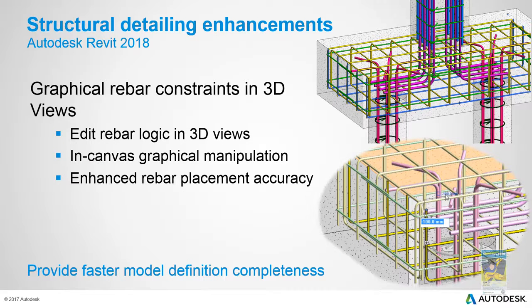And then in regards to rebar constraints, you can now modify them in 3D if you need to modify them. Sometimes it's a little easier to see and work with in a 3D view than try to manipulate that constraint in a plan or elevation view.